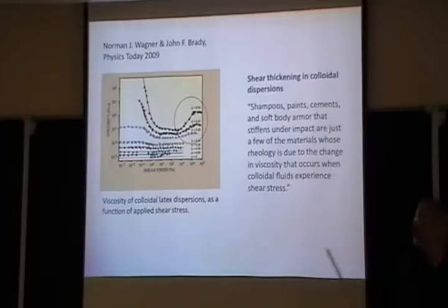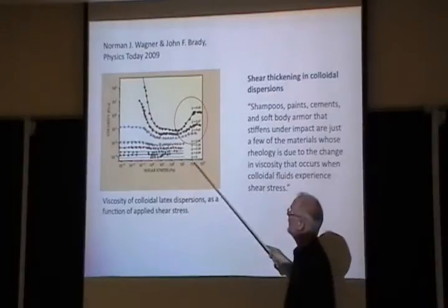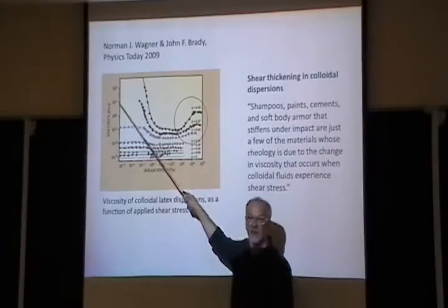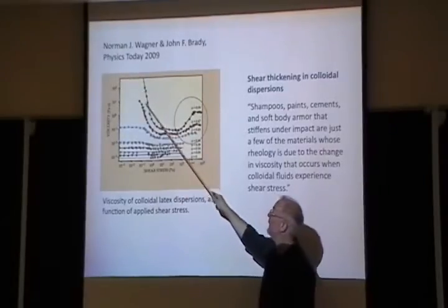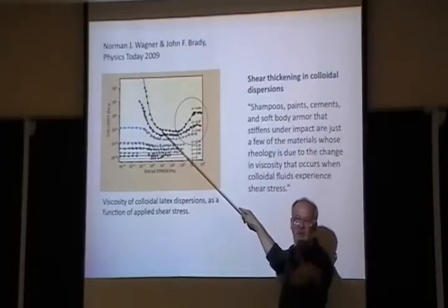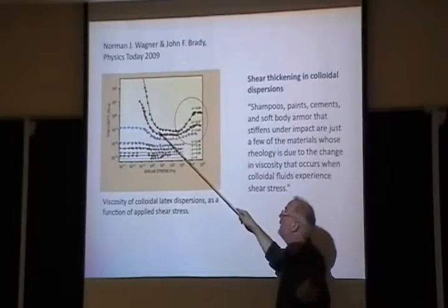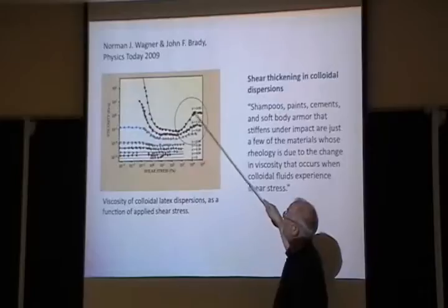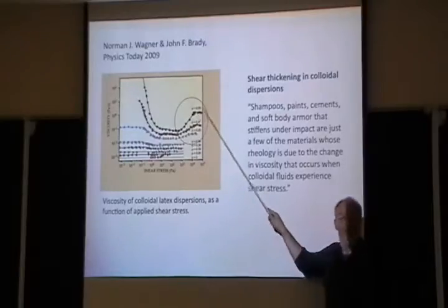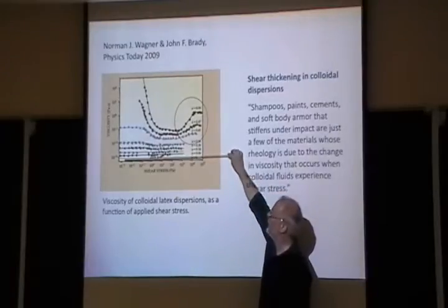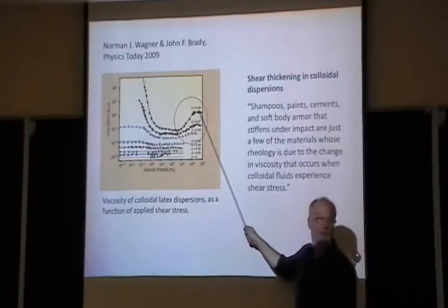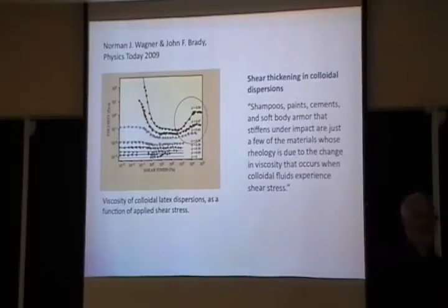So what is shear thickening? So here's this log scale, log shear stress and viscosity. Shear thinning. This would mean there's a yield stress someplace, comes down, shear thins. I mean, it's just because it overcomes the yield stress. It basically starts flowing. And then here, viscosity comes up. And the different curves are for different concentrations. If you don't put anything in down here, if you put particles in, you get up here. So what is cornstarch? Cornstarch is 10 micron particles in water. So it's about 50-50 mix that I made there for you.